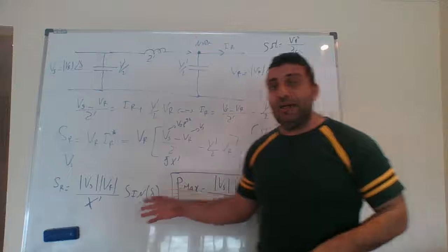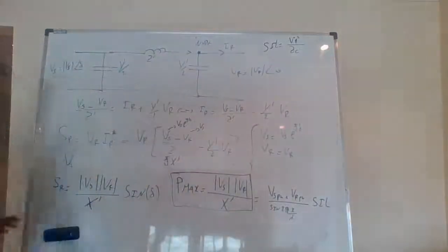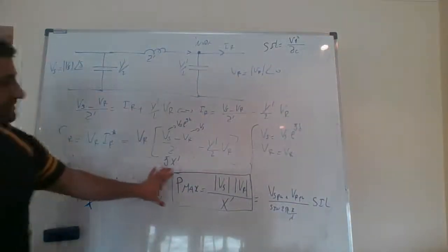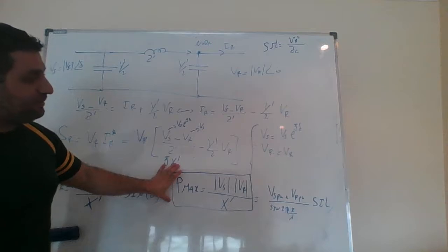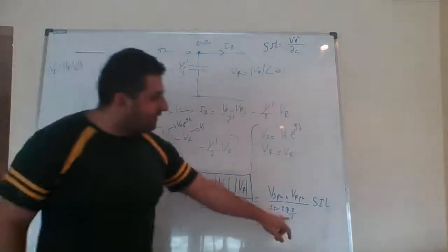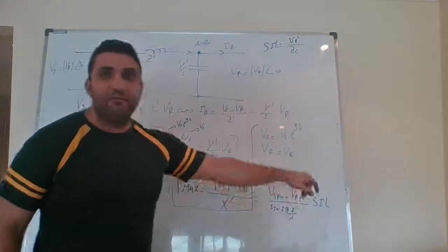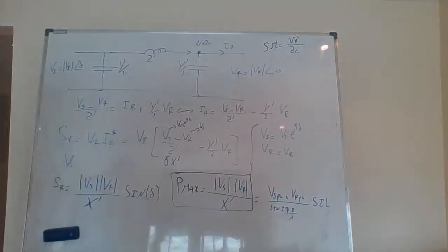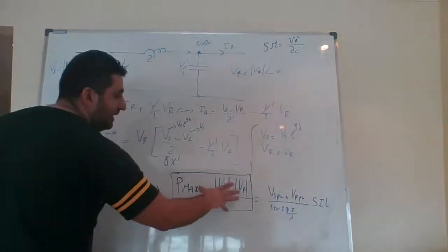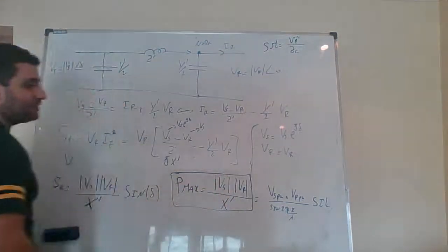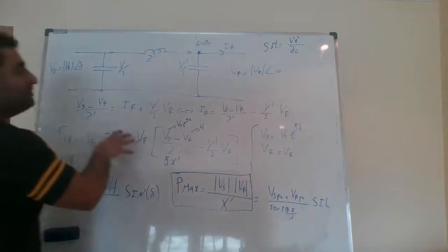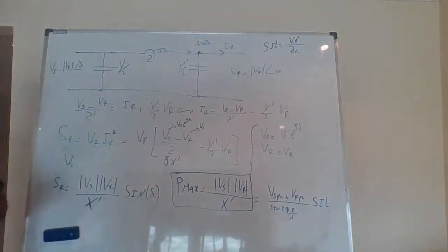And finally, I did the steady state stability. I determined the Pmax that the transmission line can withstand, which is in relation to the wavelength, the length, the surge impedance loading, and this system in here. If I try to exceed the system theoretically, I will lose the synchronization between the sending and the receiving end.